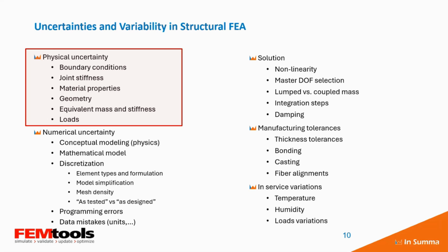So, I mean, parameters for which there is a relationship between the response and the parameter. We know that the resonance frequency is a function of stiffness, mass, damping. So we have a relationship, and that relationship can be used to compute gradients. And if we have gradients, we can use an optimizer. We can use optimization technology to find the parameter modifications that we require.